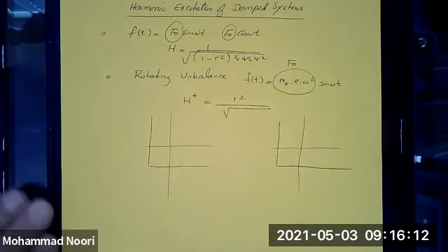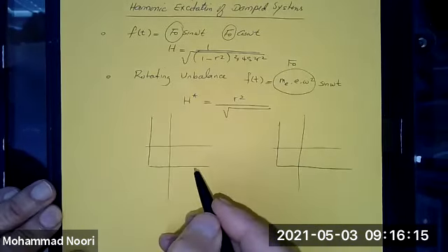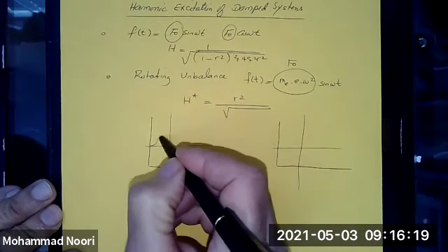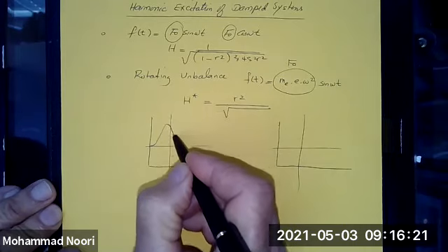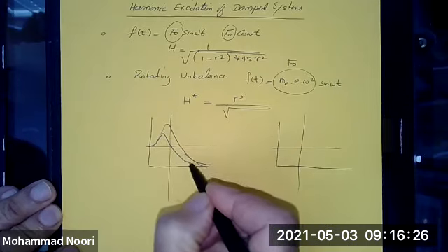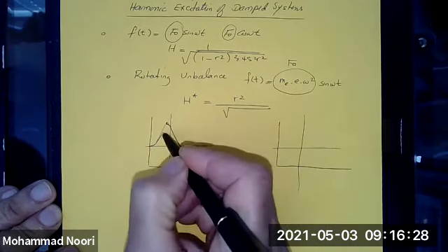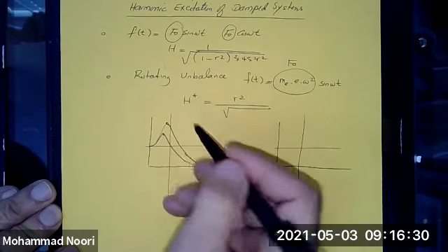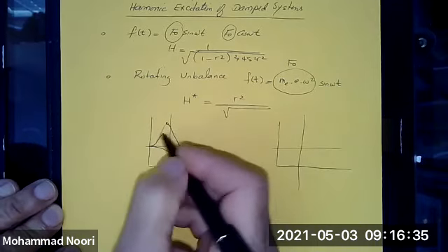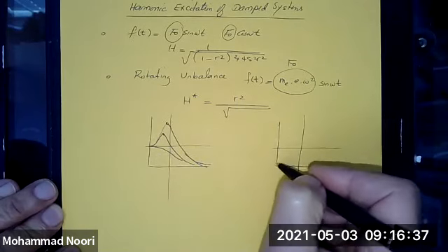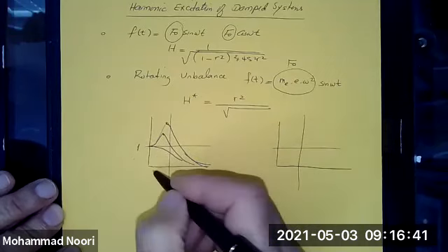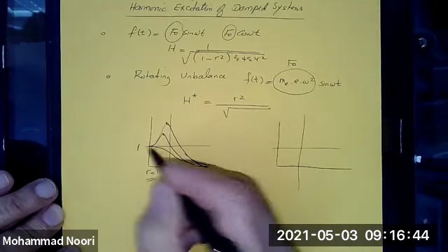And we compared these two: what happens in the case of simple harmonic excitation, or when you have an unbalance causing the displacement. The frequency response functions were quite different. In this case, the peak value of the frequency response function shifts to the left, depending, of course, on the damping ratio, and at r equal to 0, the value is 1.